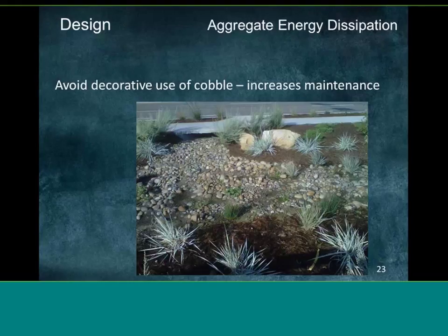If you have large expanses of cobble in a system that might have sediment coming from upstream and filling the system, it needs to be maintained. That sediment will fill into large cobble areas, and if they're not required for energy dissipation, they're just there for decorative purposes, they'll soon be filled with weeds. The weeds will establish in that sediment, and it'll become a bigger maintenance issue than if you had plants.